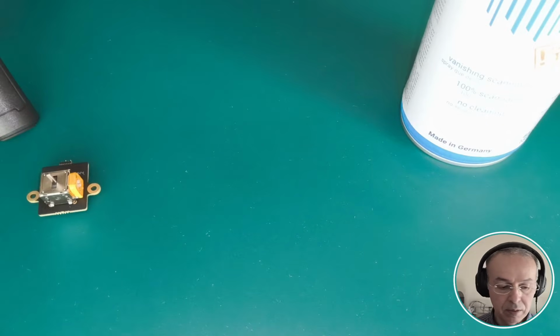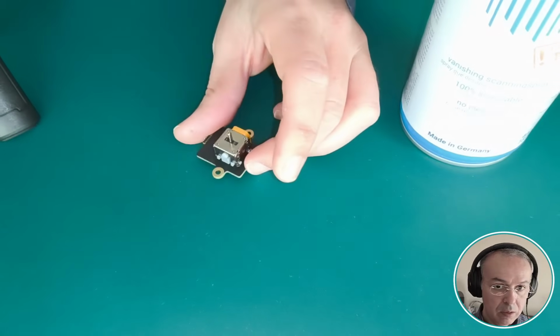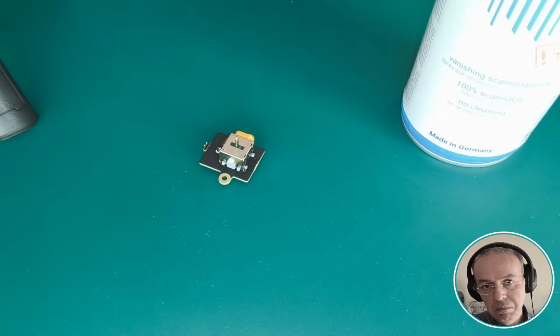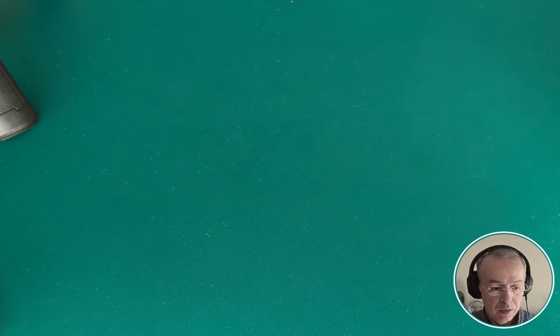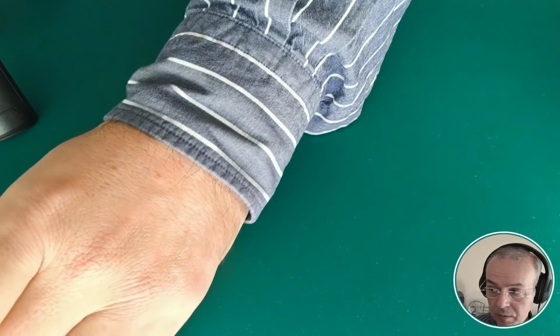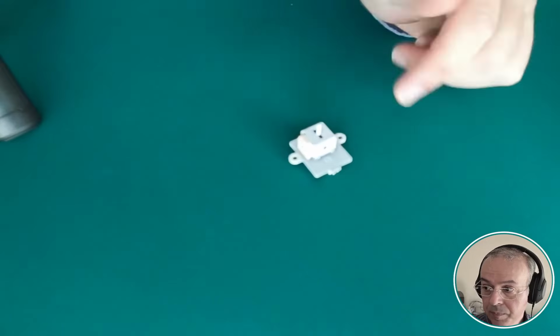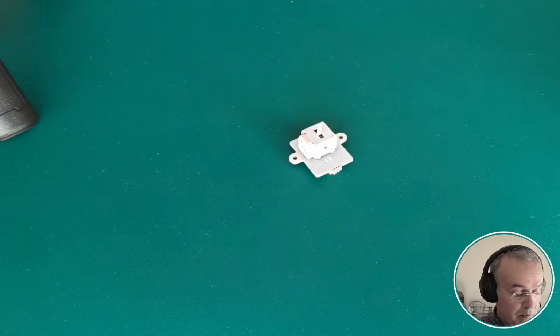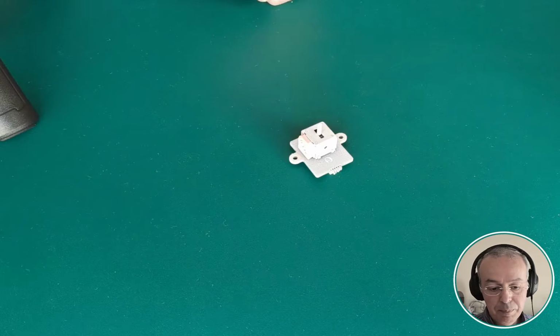So, this is the first step, and I'll scan this using a higher resolution scanner because, as you can see, the part is quite small. We're talking about a part approximately 20 millimeters in size, maybe around that. With the part already sprayed, we'll begin the scanning process. We've prepared the scanner to start the scanning process. Let me show you.